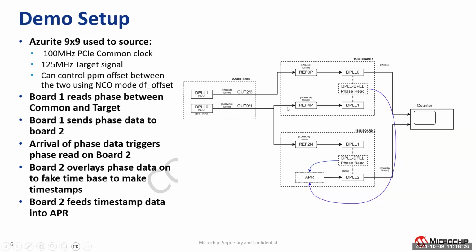And then the PCIe bus 100 megahertz signal is given. That'll always be there. And then you would need a differential PLL to be able to make those phase measurements, and something like a 1588 algorithm to control that PLL and adjust our final output.